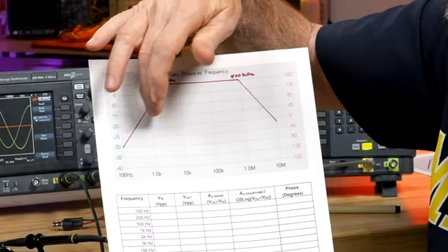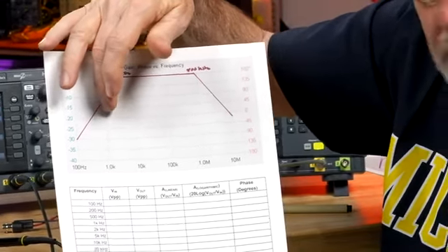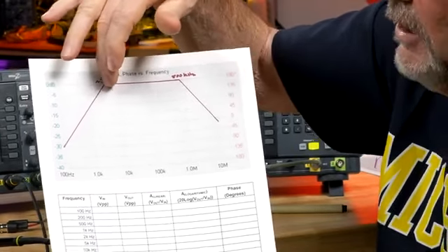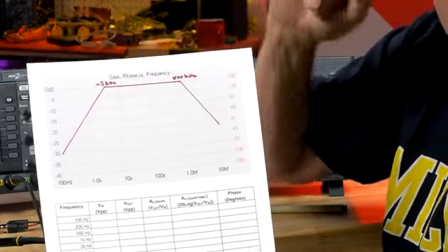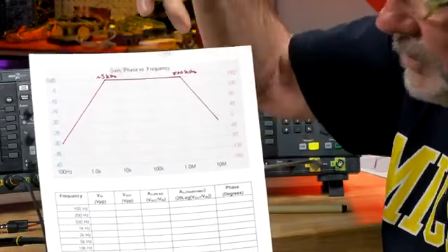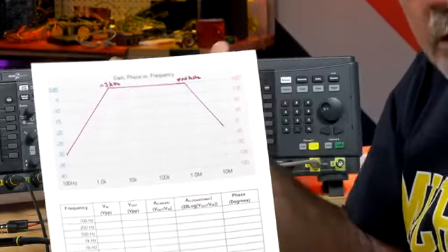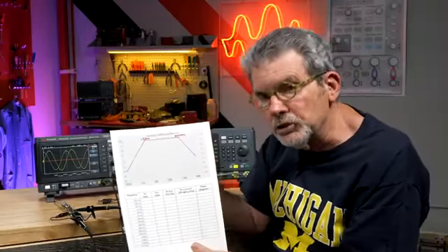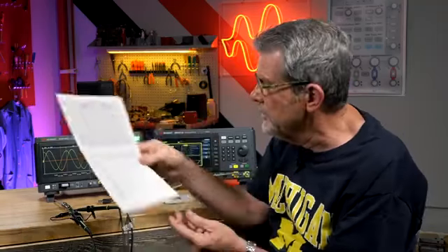So this is plus 20 dB per decade going up to where the pole is, and then it rolls off minus 20 dB per decade, which makes it go flat right at 0 dB. Then it hits the second pole and rolls off another minus 20 dB per decade. So this is the straight line approximation.